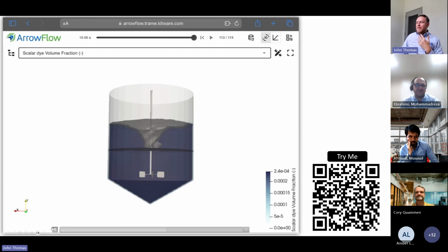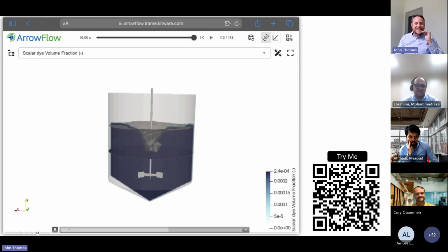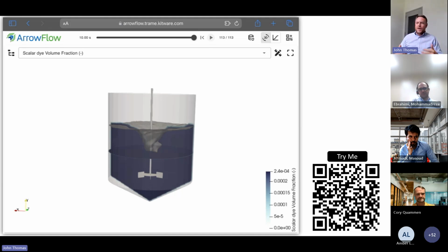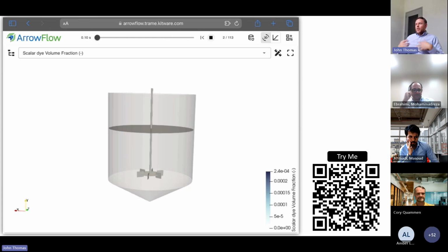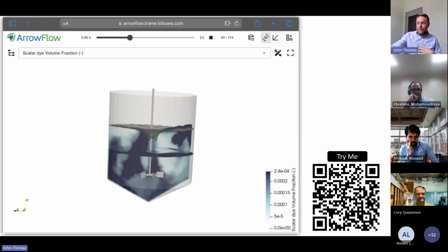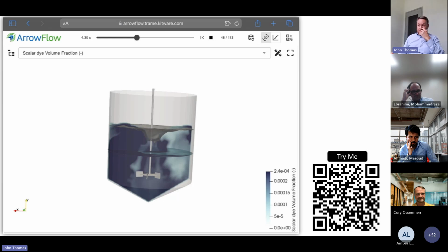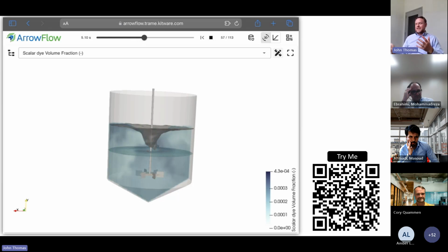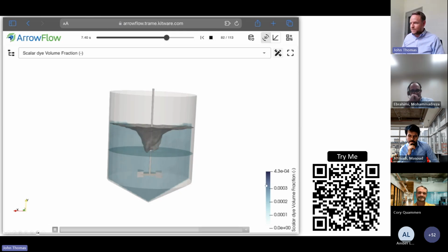And it's amazing how much you can learn within a simple simulation. Like, why did my process not aerate properly? Why did I get too much oxygen? Why did my particles not suspend? When a process engineer can see, oh, my power per unit volume is way too high, or oh, it's not a mixing problem because my blend time was 3 seconds. This would be some other sort of problem with respect to maybe process control. It's amazing how empowered they can be to optimize a process where they can answer their questions independently.